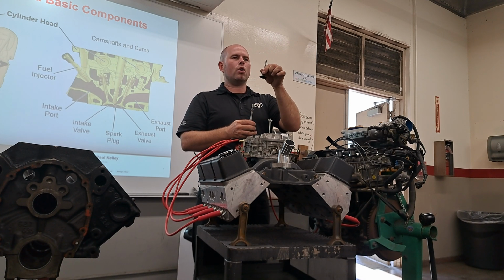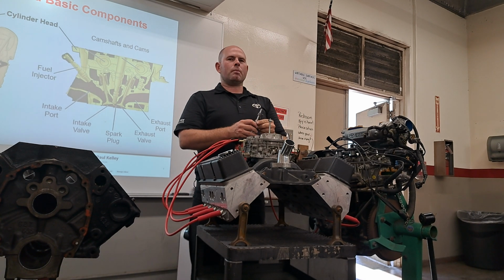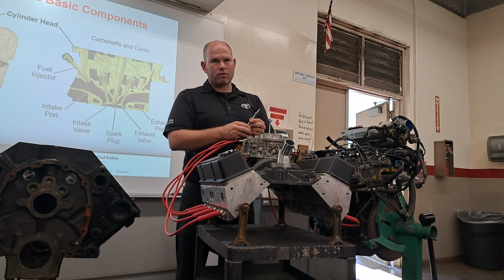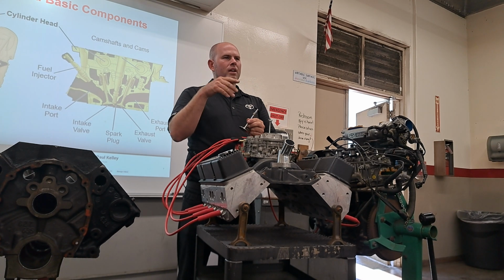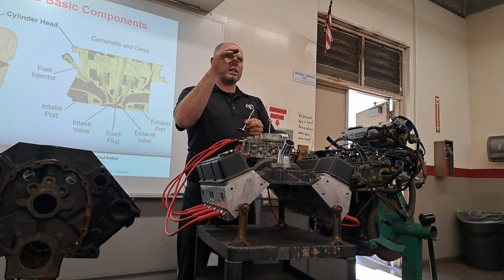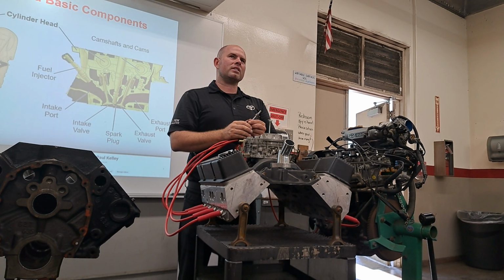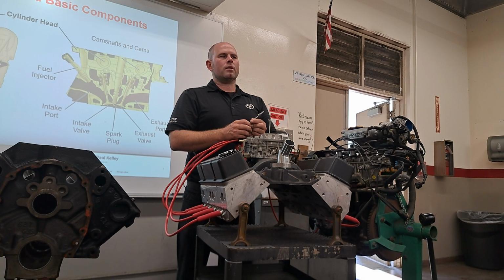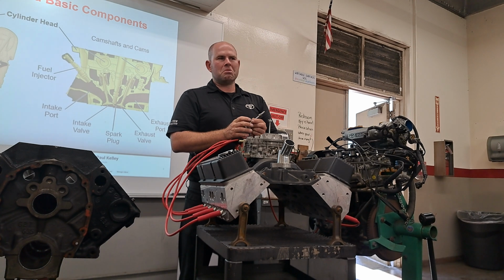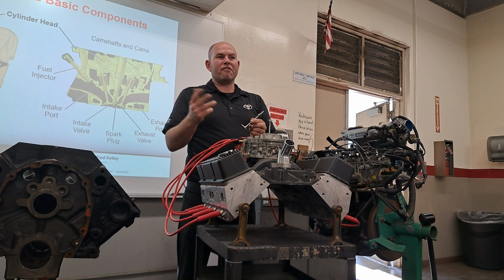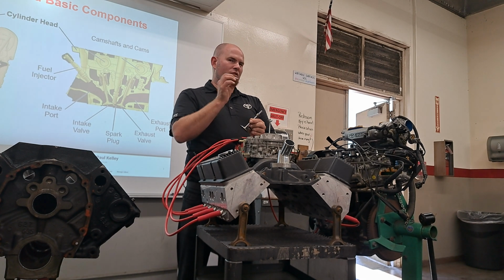So I would go to start it and it was very hard to get running. It was like, oh man, I need to do another valve adjustment. I'd go in and I'd see the valve adjustment get less and less and less, and I'd be like, I don't feel like taking it apart, I'm just going to run it for a bit longer, until the point where it doesn't really want to start. That's a dangerous point, but I said it didn't want to start because it's a 1-cylinder bike. On a car, you won't really feel anything because it's got 3 or 7 more cylinders or something. So you have 1 cylinder with the valve hanging open.